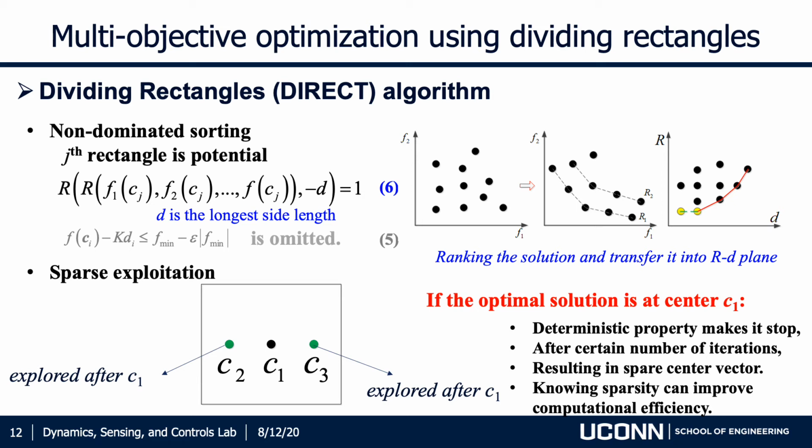So the center vector C1, C2, C3 till Cn will have many zero entries, that is, it is a sparse vector. If we can know the sparsity in advance, then the algorithm can change the searching space and improve the computational efficiency. Thus, the second objective is to build a zero norm of the damage index vector.